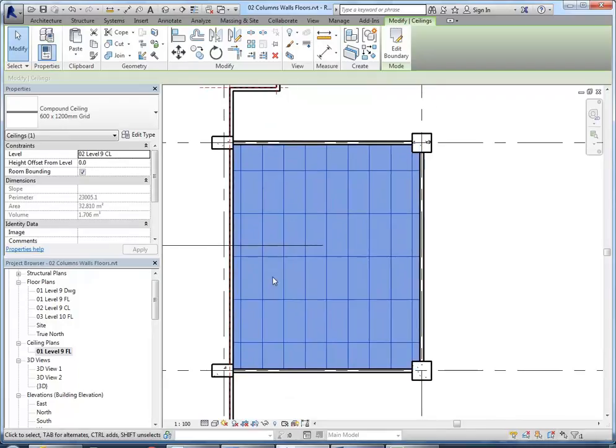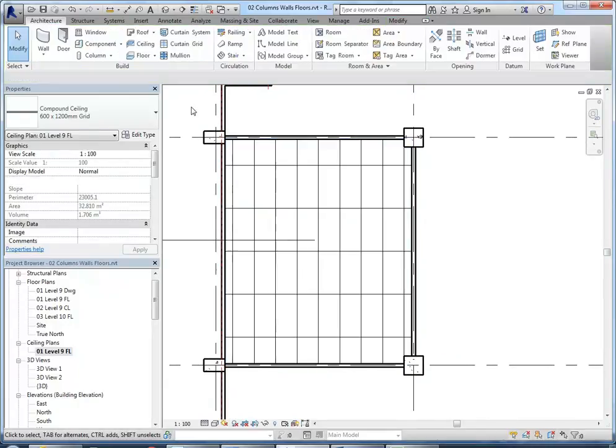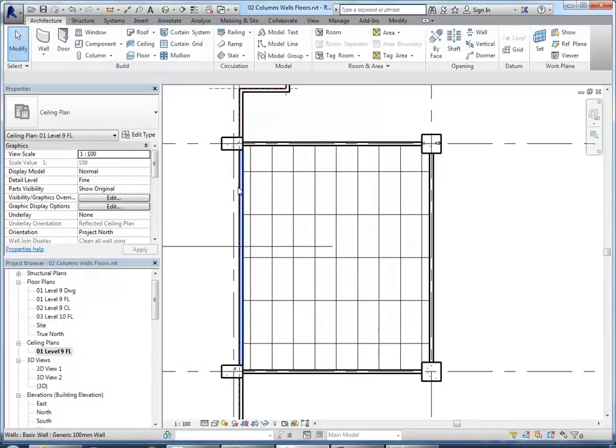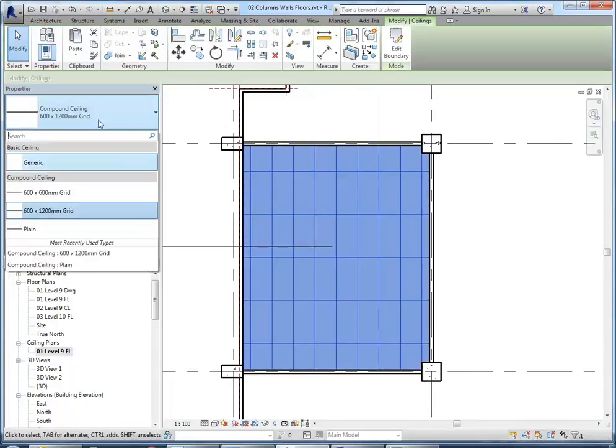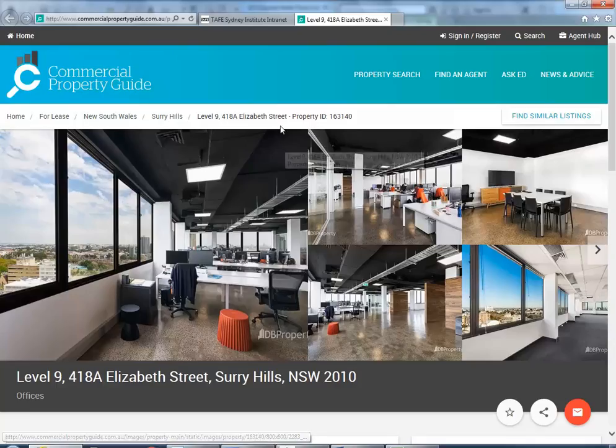And then when you place lights, let's go back to a plain ceiling, that's always an option. People think if you have a ceiling grid structure that you need to put a ceiling grid in with ceiling tiles, but you don't. You can easily affix plain plasterboard to any grid structure. So with this sort of setup, you could easily have a plain ceiling in some areas. It doesn't have to be ceiling tiles if you do want to have an actual ceiling somewhere.